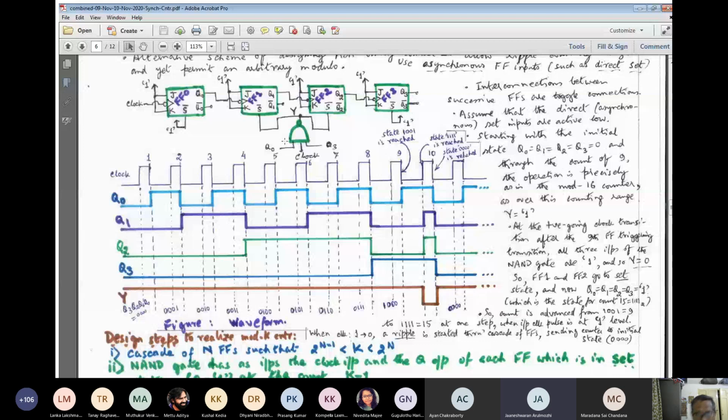Excellent, very good question. Of course, a decoding logic should be there here also. In order that a decoding mechanism is activated, normally we have a strobing signal. So some strobe signal is there. For the other states, it is not much of a problem. We can send the strobe signal at the rising edge of the clock, that means we can synchronize the reading of the state with the rising edge of the clock. So more or less it will act fine.